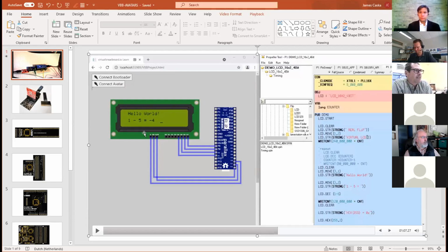Yeah, so you can also use this, even with this chip now. I've also, like I said, I'll have to do another fuller presentation, but you can use this as an oscilloscope, for example, because in this case, it's exactly what it's doing. It's using the DMA to capture the timer of the peak, and then it writes the time, does a delta on that, and uploads it over the serial, so to speak. So each is like a component driver. Each driver depends on how you want to do it and what features are available.